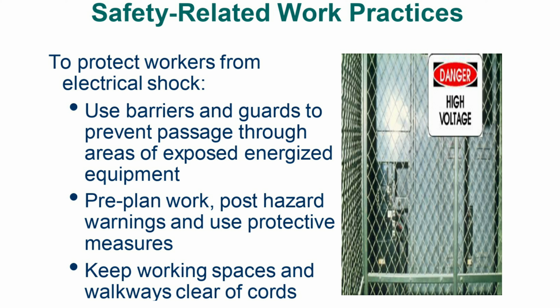Safety-related work practices: to protect workers from electrical shock, use barriers and guards to prevent passage through areas of exposed energized equipment, pre-plan work, post hazard warnings, and use protective measures. Keep working spaces and walkways clear of cords.